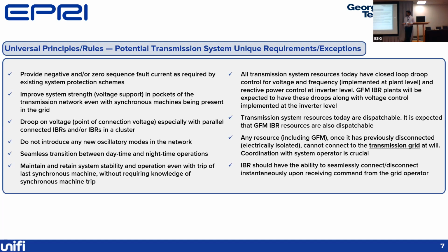Now, there are some aspects here which we still don't know how we would test or how we would verify, because not introducing new oscillatory modes is very much system dependent, very much dependent upon the rest of the other devices that are present in the system and how they may interact with each other. So how we would exactly go about testing this, we still don't know yet. That's what we'll keep working through the consortium. But we want to try to ensure that the newer inverters that are coming into the network will not introduce any newer oscillatory modes, and also seamlessly transition between daytime and nighttime operation.